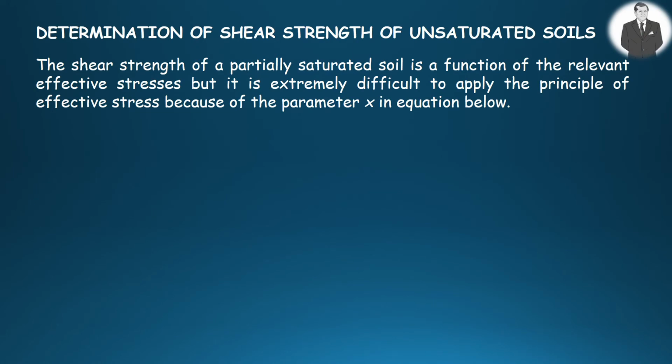Shear strength of unsaturated soil, in other words, partially saturated soil, is a function of the related effective stresses. But it is very difficult to apply the principle of effective stress because of the parameter chi in the equation given here.